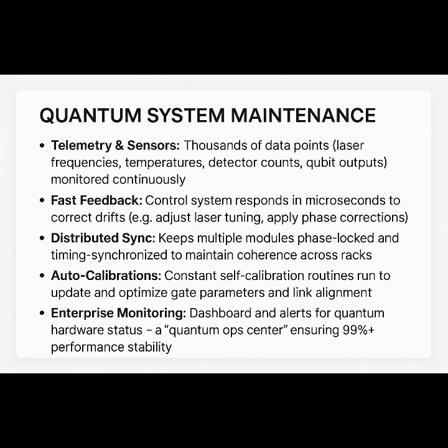In a modular system, similarly, one might measure a link fidelity in real time and adjust a parameter. For instance, if a photon detector is registering more background counts than expected, the control system could momentarily increase a discrimination threshold or trigger a recalibration of that detector's baseline.